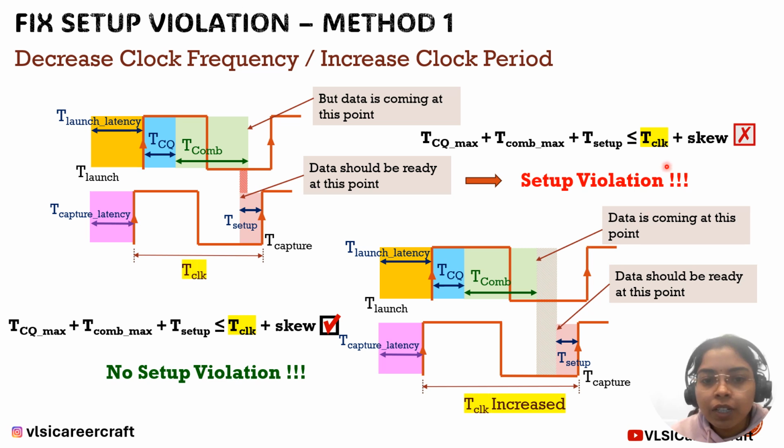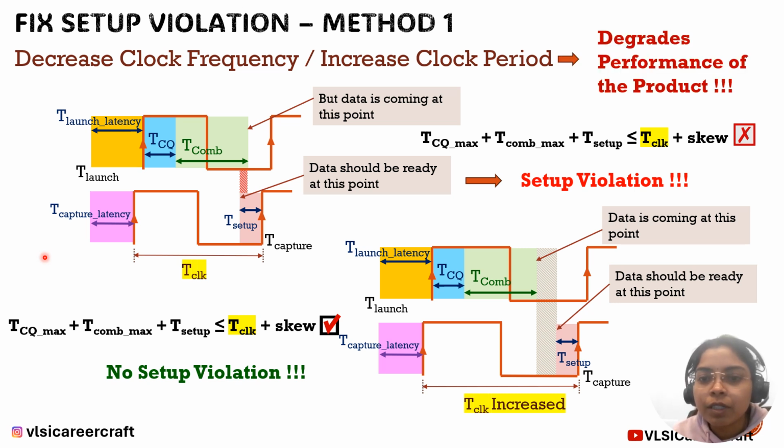But what is the problem with this method of fixing setup violation? We are decreasing the clock frequency, that is, we are slowing down the system, we are decreasing the speed at which the system is operating. So this degrades the performance of the product.